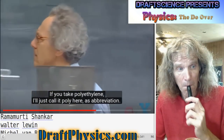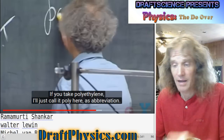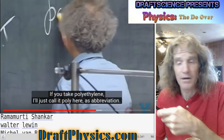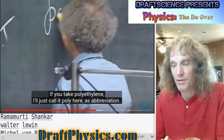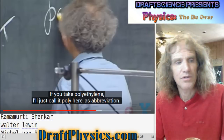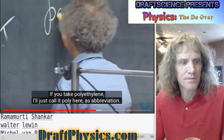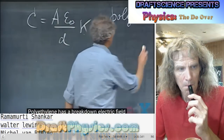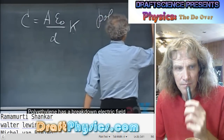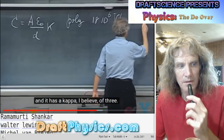If you take polyethylene, the ions move, essentially, is a way of saying it. The ions are way too free to move somewhere, and so the attractive force will wipe out your charge. I mean, the ions will combine into dipoles. I just called it poly here, just as abbreviation. Polyethylene has a breakdown electric field of 18 million volts per meter, and it has a kappa, I believe.